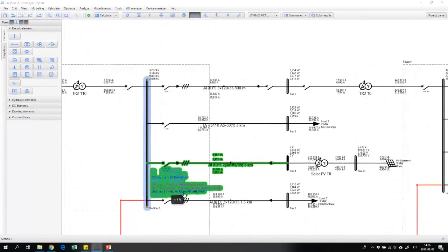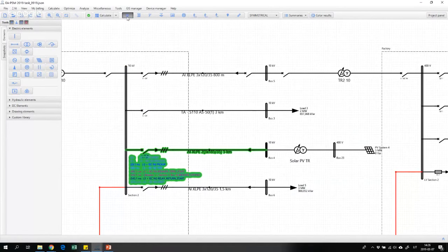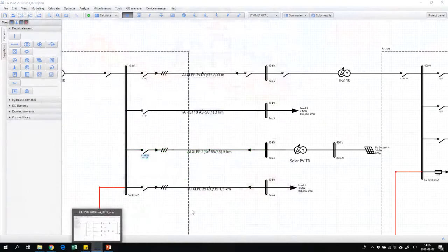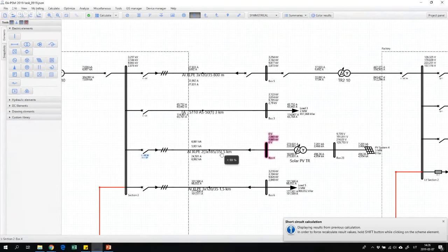When we do a solar power plant integration study, we are always asked to do protection coordination and to calculate short circuits, because short circuit currents are not only needed for protection coordination, we also need them to estimate how powerful our network is.